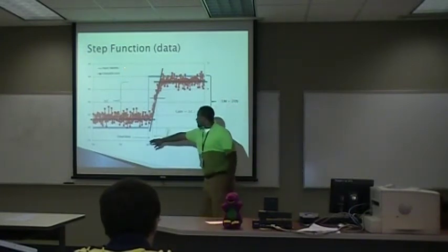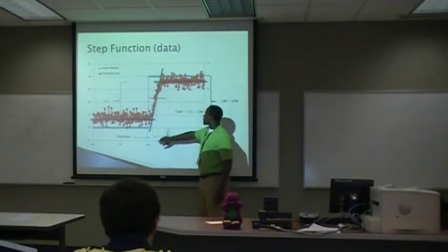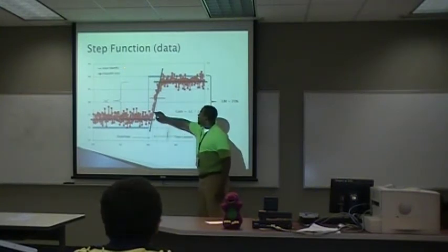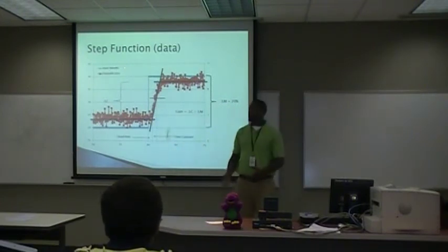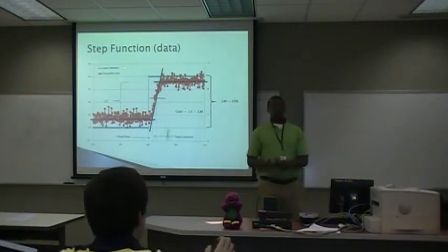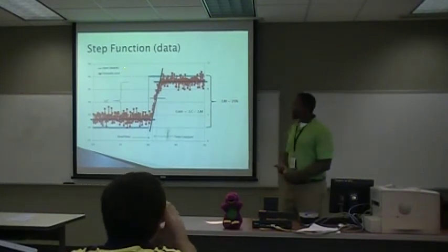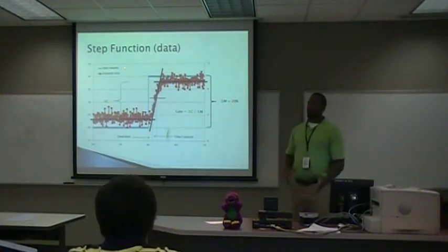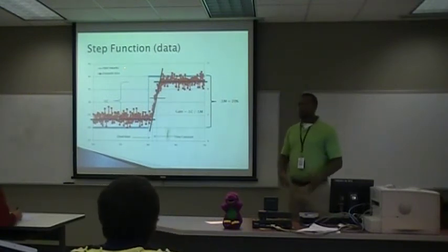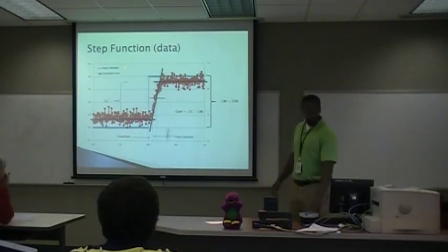The dead time was analyzed and the time constant was analyzed from noticing when the slope was made of the highest slope that was made of the response. And from there, we were able to calculate the time constant, the dead time, and the gain of the system. And we looked at the middle ranges, the lower ranges, the high ranges of the entire system.